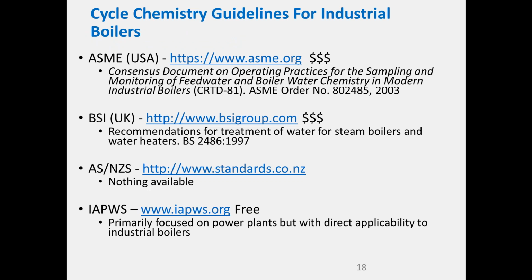So if you need some guidance, there are some guidelines out there for boilers. ASME in the US has a guideline that you can purchase. It's the consensus document on operating practices, maybe a couple of $100 New Zealand for that. The BSI, the British Standards, have another one, recommendations for water treatment for steam boilers and water heaters. This is quite old and quite out of date. You can purchase that as well. For ASNZ standards, there's really nothing available.